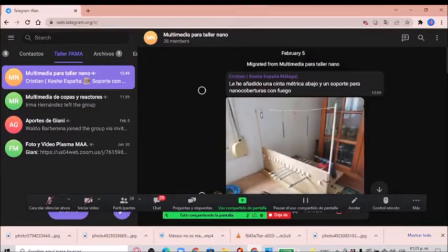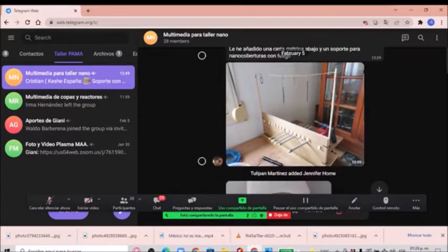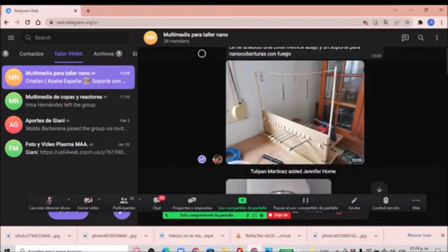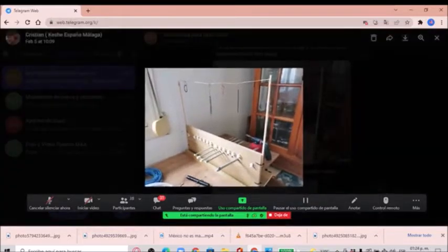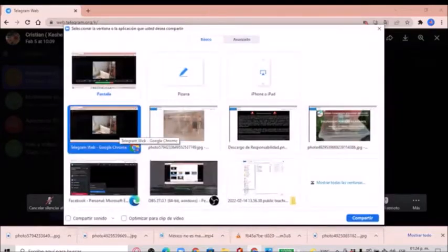Later on, we're going to teach you how to do the nano coating on zinc plates and wires, which is done in a much more diluted way of caustic soda, because the zinc will be chewed up by the caustic soda practically immediately. You need to work very fast there, and with very low concentrations of caustic.